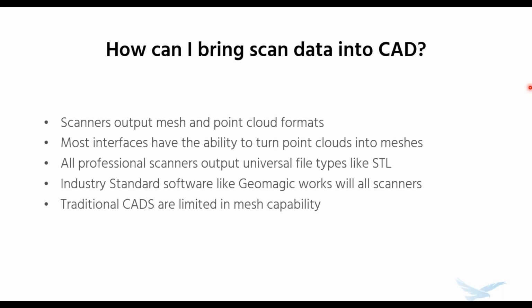And as far as traditional scans go, most CADs can input an STL, and sometimes a few other mesh formats, like SolidWorks can also open OBJ. That said, most traditional CADs are pretty limited in their capabilities with it. So I kind of view this like a multi-tool: if you broke down in the middle of the desert, you would be really happy to have your Leatherman tool on you, but you're sure not going to use your Leatherman tool to rebuild your engine back at the shop.